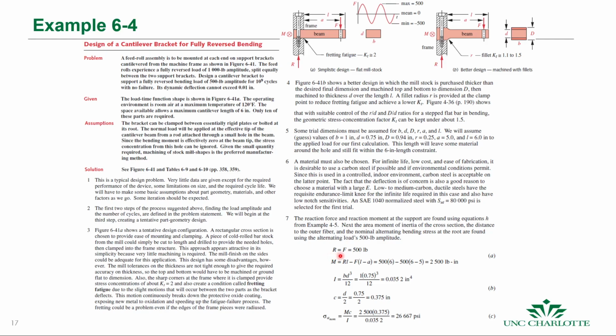The reaction force is equal to the applied force. The applied force at the distance provides us with a moment, which we can calculate here. We can calculate the moment of inertia and the distance to the outer surface of this beam, so that we can use the flexure formula here, Mc over I, to get our nominal amplitude of oscillating stress.